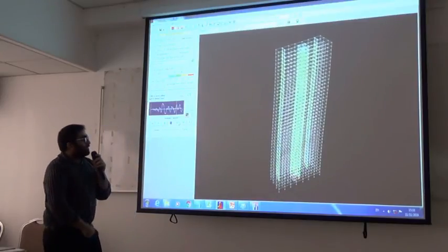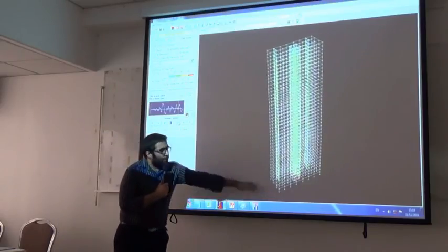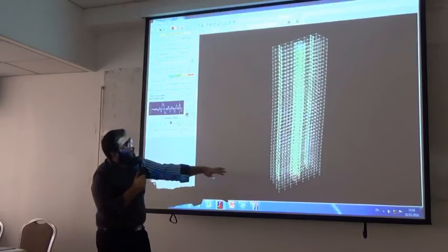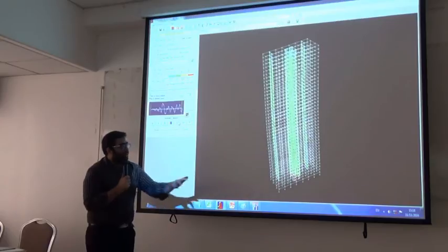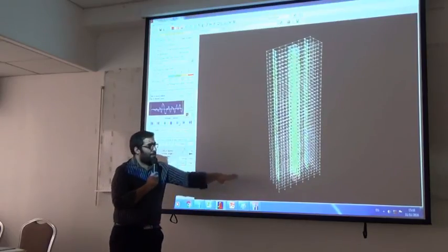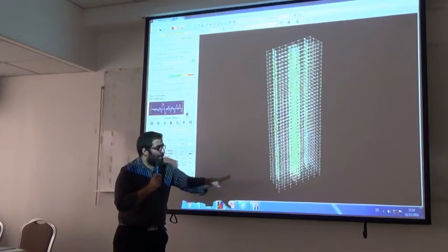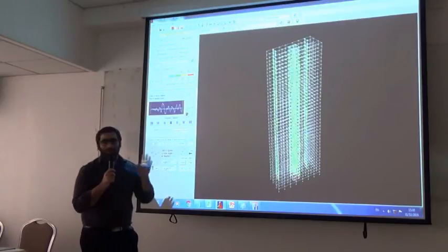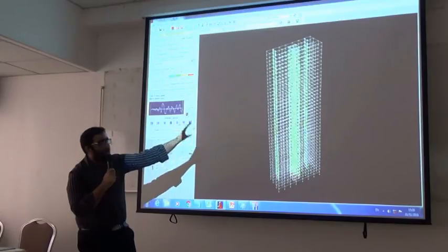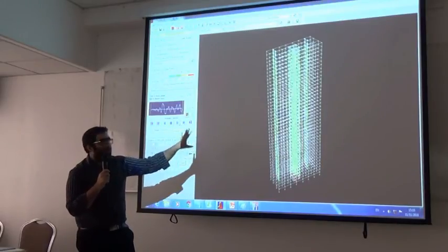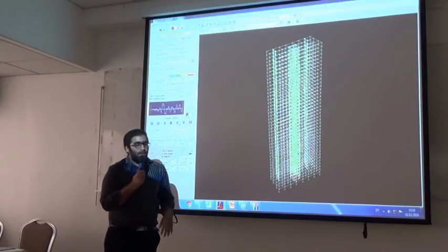Now in this model, we can see that the wall is only yielding at the base. There is no yielding in the upper region of the wall. Normally, the yielding of the wall in flexure at the base will always happen when the wall yields in the first mode, because the moment for the first mode is high at the base, right? If you see some yielding high above, that will correspond to some higher mode effects. But this building does not show a behavior like that, right?